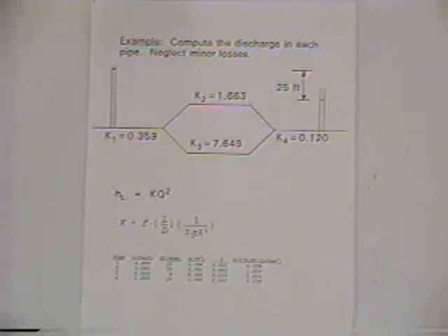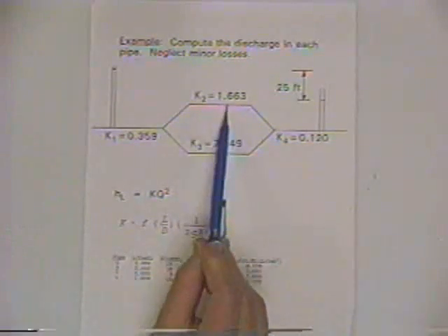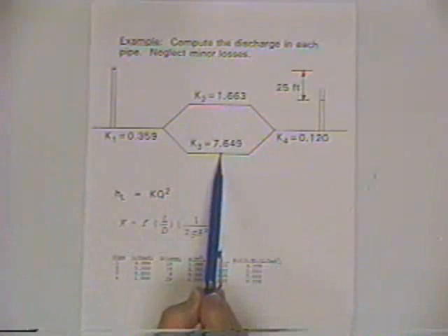Those are the concepts. And the rest of it is algebraic manipulation, which can take on a lot of different forms depending on how one wants to present the formula. So you've got to use a little bit of ingenuity to combine those basic relationships that you know to solve whatever the problem might be. And so the first thing we're going to do, we're going to say the head loss in pipe 2 is equal to head loss in pipe 3.